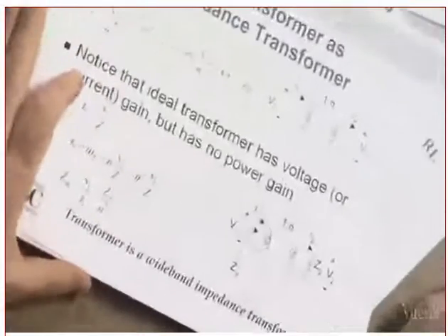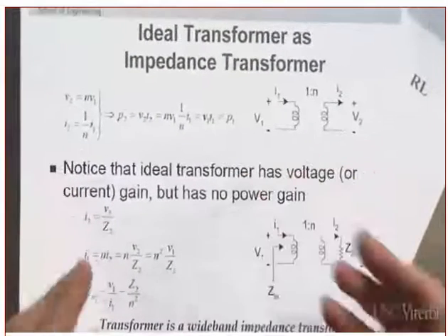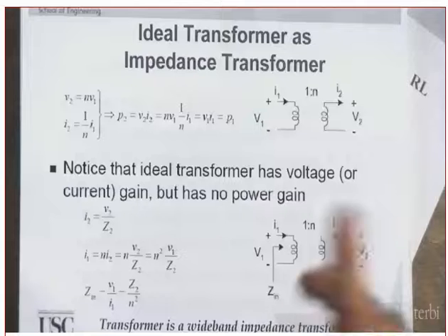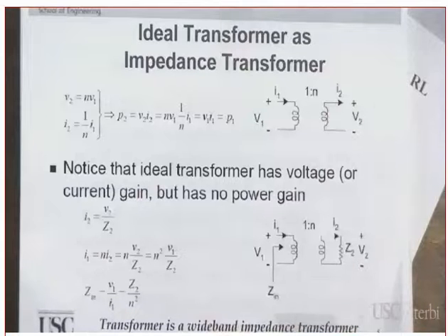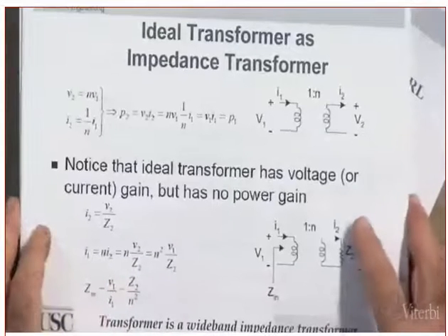Clear? Okay, good. Now, let's see. How come incorporating the inductors that I neglected will not affect my matching circuit? The matching was based on a pure resistive load. It was not based on an inductive matching. So when I get a certain resistance and a certain inductor, I can simply lump it with the other one, which will not have any effect on the transformation. By the way, I will show you that. Your question is premature. Can you be patient a little bit? We have not even talked about the L match yet. Okay, good. I will get to all of these in just a second.